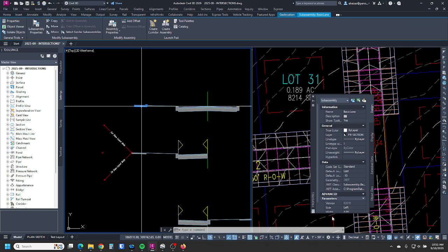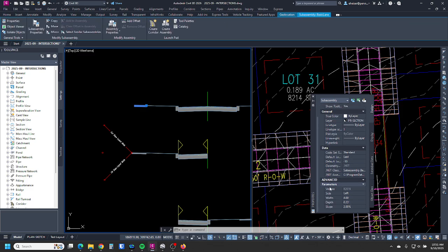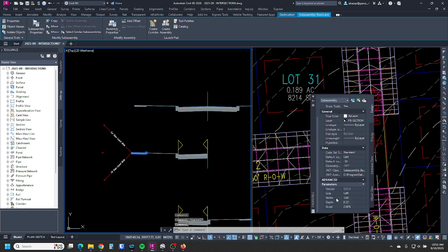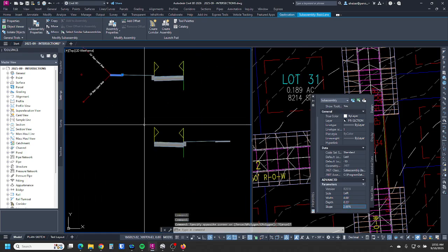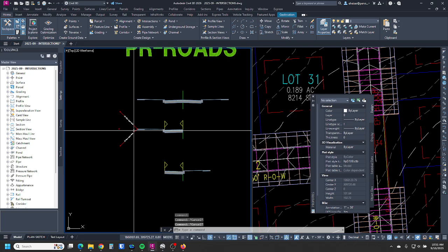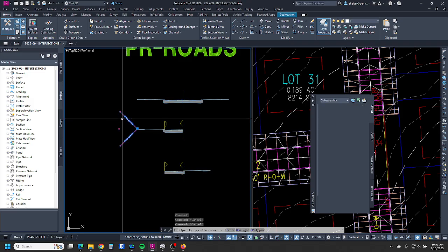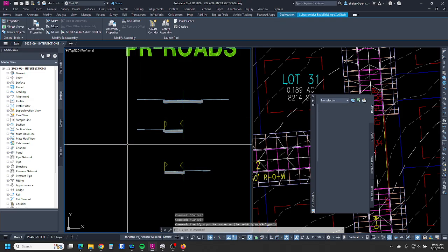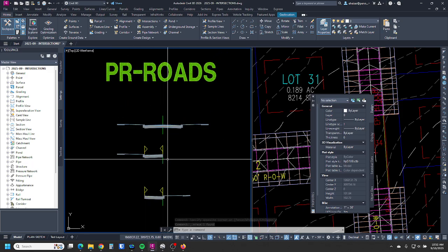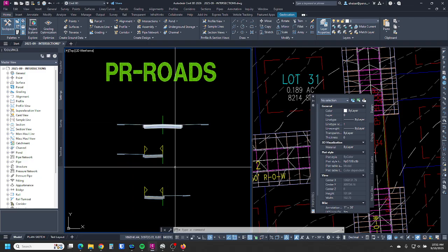And then we'll do the sidewalk, which the property parameters for that has a 4-foot width at 2%. So we will select the sidewalk in the half section, make it 4 feet wide at 2%. And the same thing for the curb return, 4 feet, 2%. And for this exercise, I'm going to delete the daylight subassembly off of this. So these are your finished assemblies for this exercise.